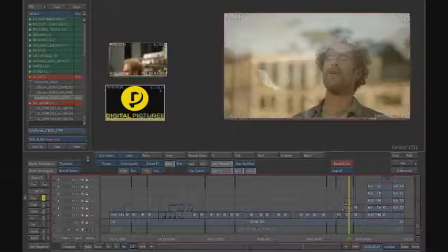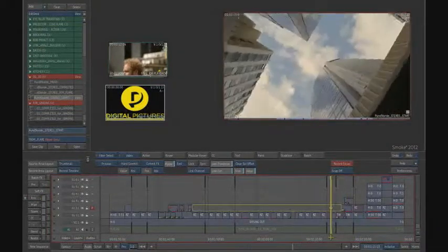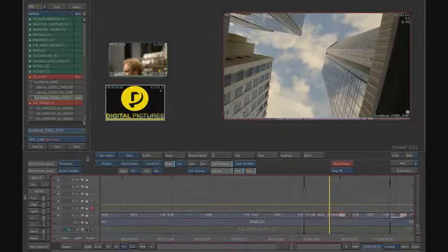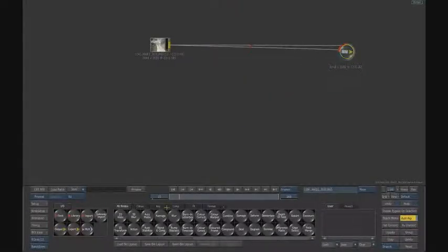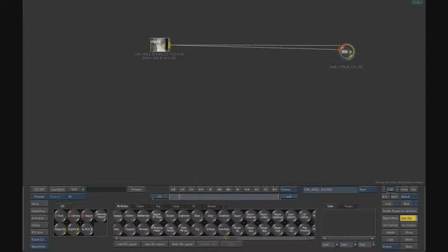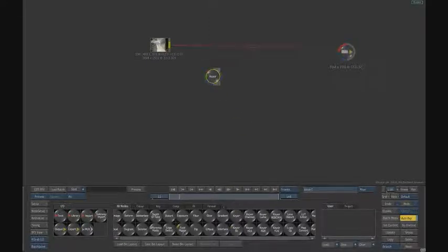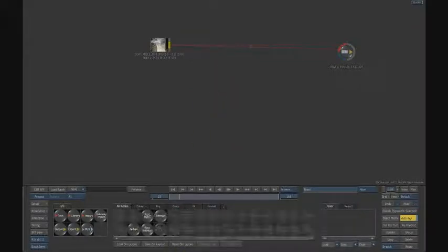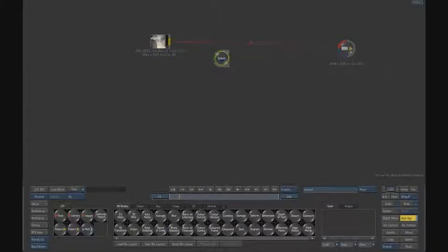So what about shots that are not visual effects shots? If you take a look at some of these raw shots here, we can actually use our batch effects environment. That's the full batch environment of Flame, even though we're working in the Flame Premium timeline here, to pull out individual procedural nodes and do any of these functions in stereo. So we can work procedurally in stereo here, but specifically we want to pull out our action environment, which has a special stereo function where it can take a mono source and produce, via that stereo camera we just saw, a stereo result. So if I plug it in here, this feeds back into the timeline for this particular shot.